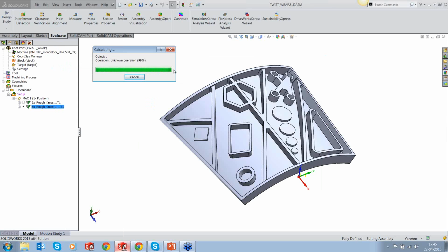So what this would basically do is generate a toolpath that would go into the material in one full step, use the full cutting length of the tool, and try to create as many spiral toolpaths as possible depending on how the geometry is in this particular part. So it could create 6, 7, or even 10 different localized toolpaths for this particular part, depending on how the whole thing looks.